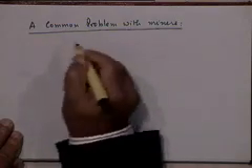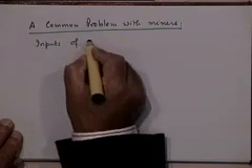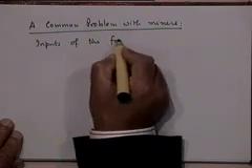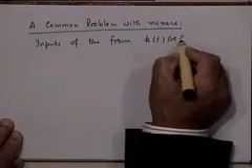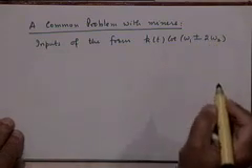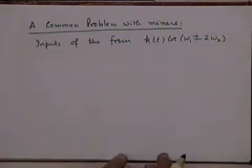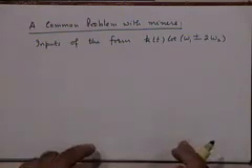And this problem is the following: that inputs of the form kt cosine omega 1 plus minus 2 omega 2, here I had taken the mixer frequency, the local oscillator frequency, to be omega 1 plus omega 2. If I had taken omega 1 minus omega 2, then the image frequency would have been omega 1 minus 2 omega 2, right? Basically the sign would be the same.